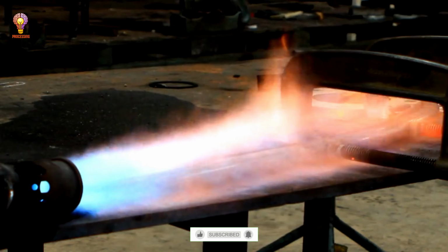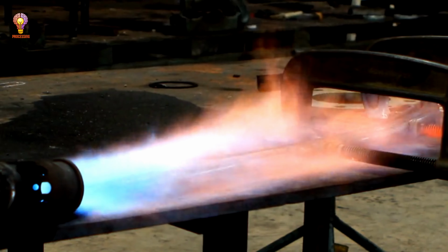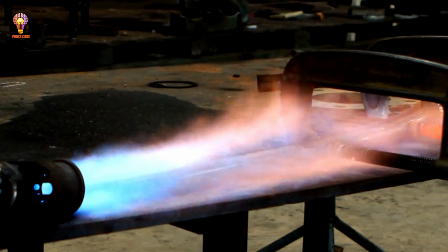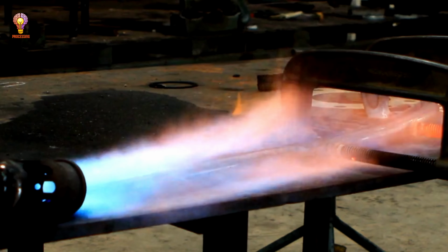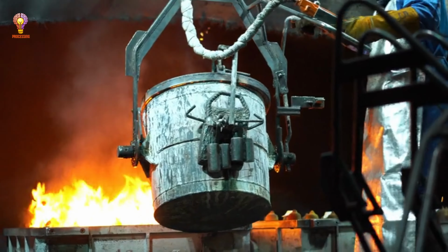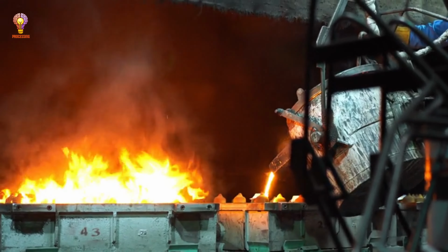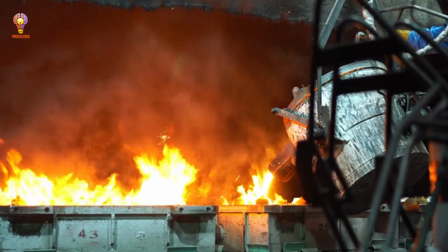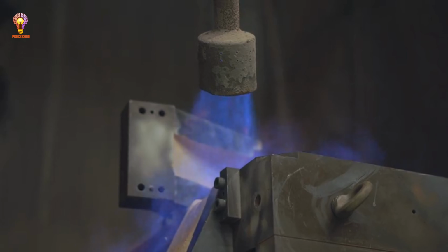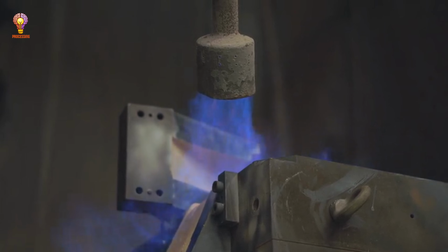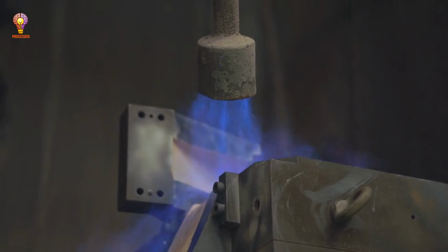Plasma arc steelmaking. Plasma arc steelmaking is another advanced method where an electric arc created by plasma melts the metal. This method has higher efficiency compared to conventional electric arc furnaces (EAFs), and it can process scrap metal and certain iron ore products directly. The high temperatures in the plasma arc make it ideal for melting and refining various metals, including specialty alloys, with lower energy usage.